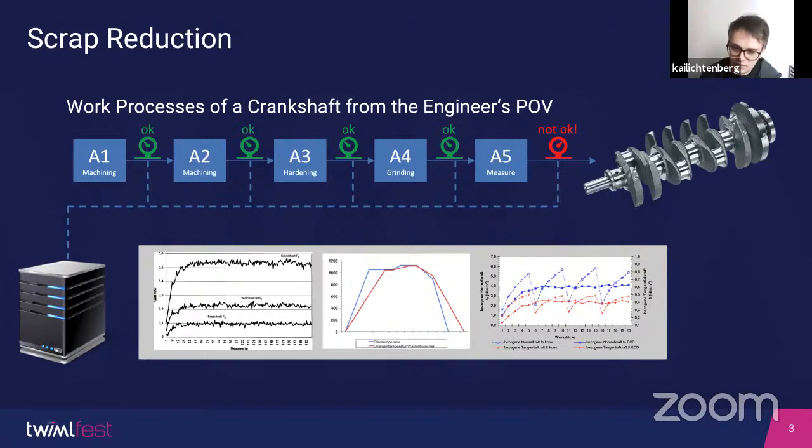And those surfaces are then gradually brought onto the shaft in various milling and turning processes, and then the surfaces have to be hardened. Yeah, they really have to be very hard. And then the last step is accurately grinding those surfaces so they are very, very precise. And they have to be precise, they have to be hard, and they have to be smooth so that they can rotate in the engine without any problems.